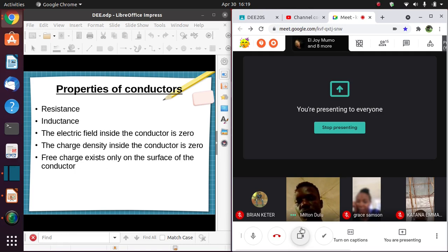Now, these magnetic fields interact. There are linkages of flux. The lines of the magnetic field are called flux. So there is flux linkage, they interact. So what happens is that there is a voltage, an EMF, induced in that conductor. Now that EMF that is produced will oppose the current that is causing that EMF to be produced. So if current is flowing in this direction, the induced EMF will be flowing in the opposite direction. This is what we call inductance. Are we together?